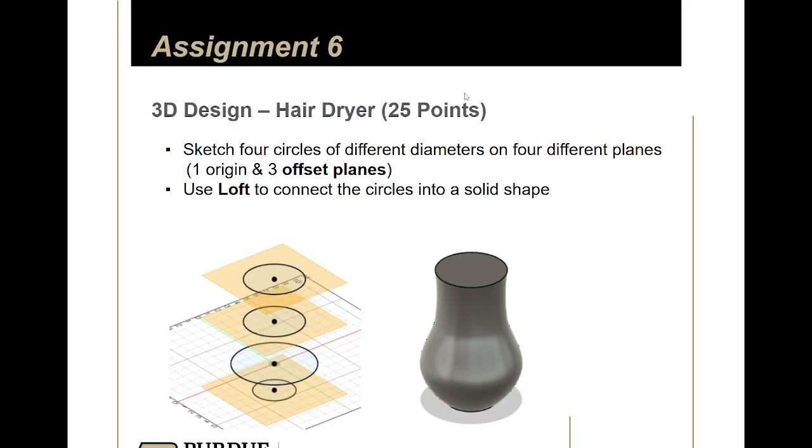we're gonna approach this in kind of a different way than we've been making our other stuff. In this case, we're going to be using a loft. So if you look at this profile here, there's a couple of different ways you can make it, right? Before, if you ignore the loft tool, you could create this profile by using a revolve, right?